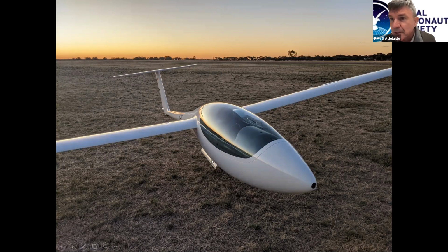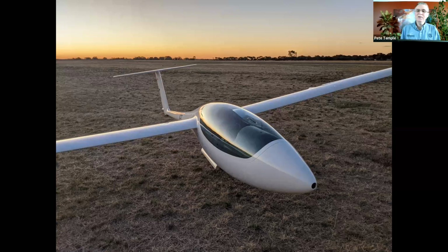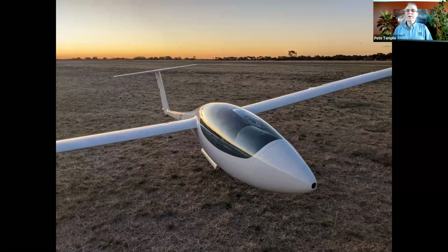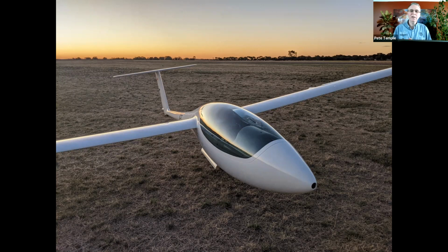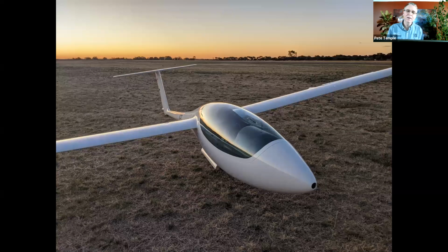I've got another question from Peter Champness. You're coming from a very high and a long way out. What safety height did you program in to be sure of getting home? I actually can't remember on this particular flight. So for the non-glider pilots out there, the safety height is the height that we aim to arrive back at the home airfield at. So we have a final glide where we're gliding back to the home airfield, and you could program in a safety height of 0, which means that if all goes well, the glider performs as it should, and you don't find any sinking air, you'll get back there at ground level, which is probably not a very smart thing to do. So we don't do that.